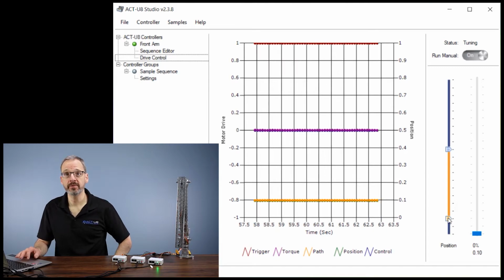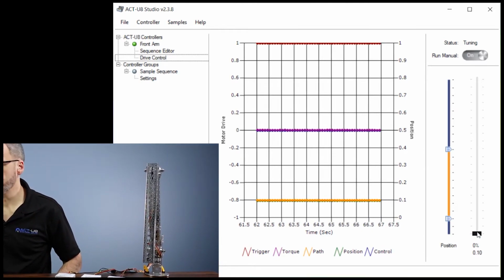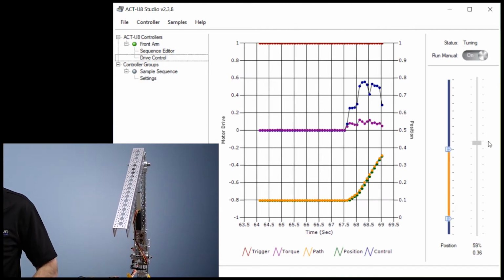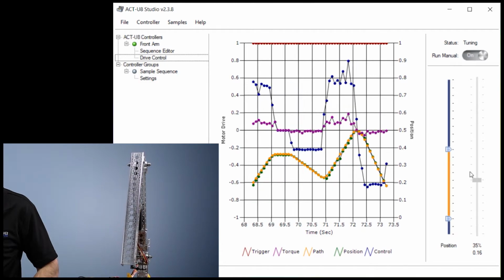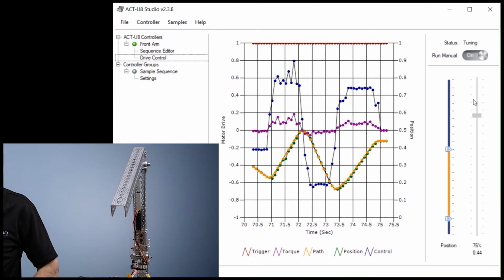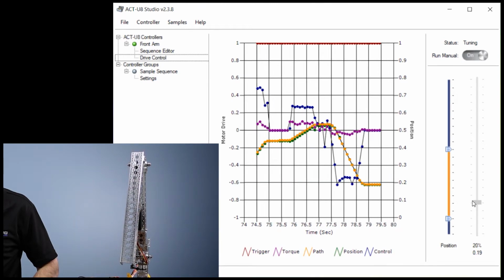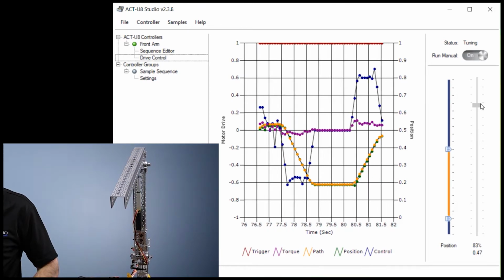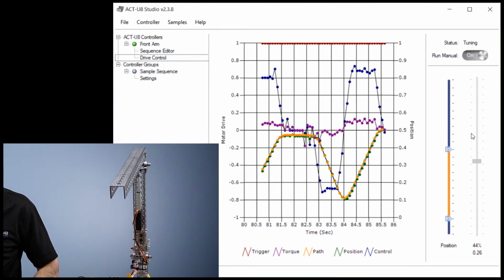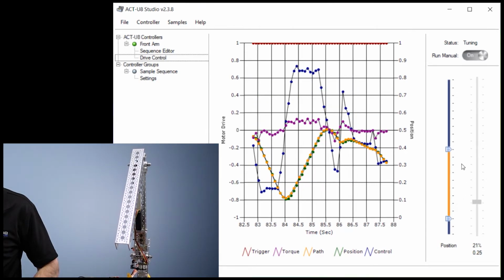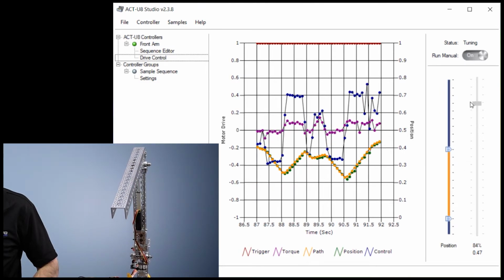And so now that you've got those two limits set, you can drive it in manual mode, really anywhere in those ranges, and it's going to respond to you. As quick as you move, it will attempt to set a trajectory which achieves that new set point without jerking the linear actuator or the arm. So you can see that. And as fast as I move it, it's not going to violate that. It's going to try and smooth it out.